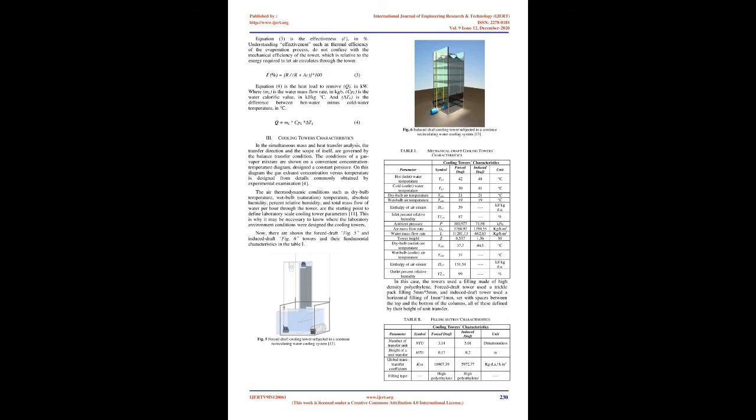6. Recirculation. It is an undesirable situation when wet bulb temperatures are affected by some portion of the saturated air leaving the tower being induced back into the tower air inlets. Although wind is the primary cause of recirculation, the following other aspects of cooling tower design and orientation play an important part in its reduction and control. A. Tower shape. B. Orientation with prevailing wind. C. Air discharge velocity. D. Fan cylinder height and spacing.